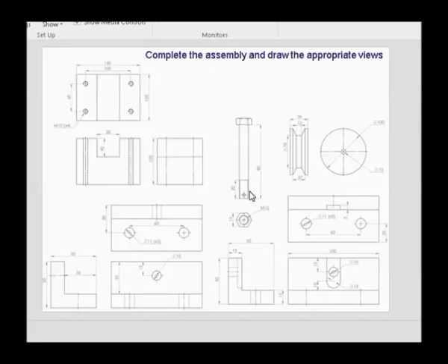To the right of that we've got a bolt, M10, so it means the diameter of the bolt is 10 millimeters with a metric screw thread at the end. The thread has a length of 20 millimeters, and there's a small hole drilled through the thread. Usually if you see a thread with a hole drilled through it, you know that a castle nut and split pin will be used. To the right of that we've got the wheel.